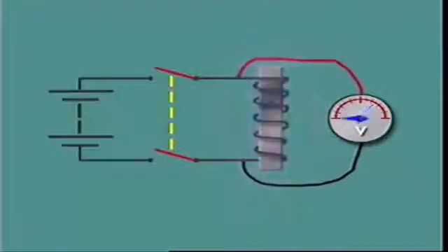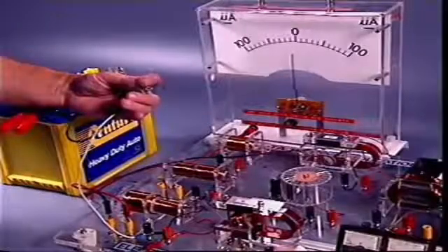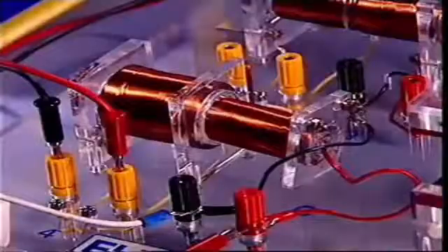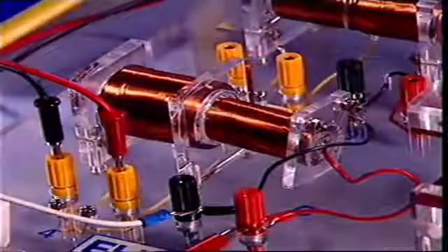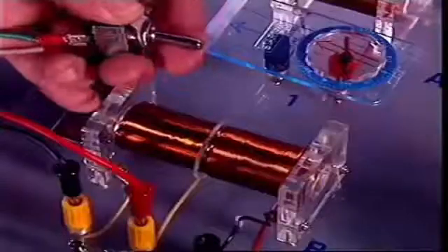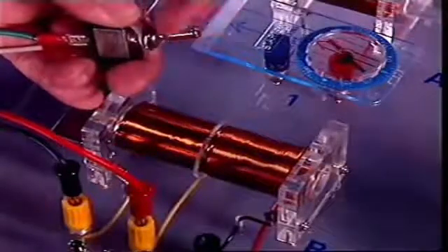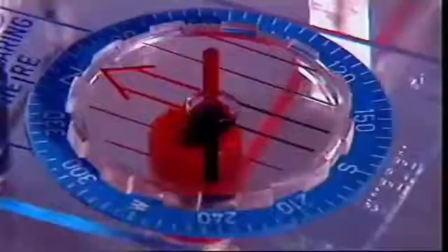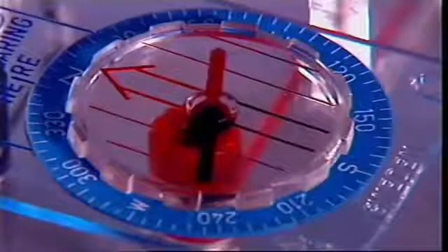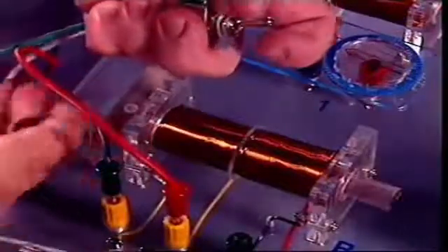This is called self-induction. Start, stop or change the rate of current flow in a conductor which is positioned close to a second conductor. This is called mutual induction. When any of these methods is used to induce voltage in a conductor, the value of that voltage depends on the density or strength of the magnetic field. The stronger the field, the greater the induced voltage.